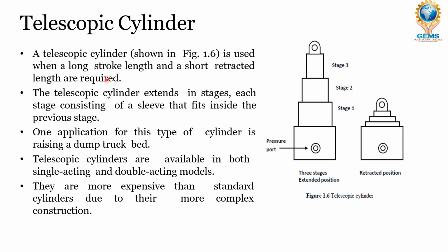So now let's see about the telescopic cylinder. A telescopic cylinder is used when a long stroke length and a short retracted length are required. A telescopic cylinder extends in stages, each stage consisting of a sleeve that fits inside the previous stage. One application for this type of cylinder is raising a dump truck bed.